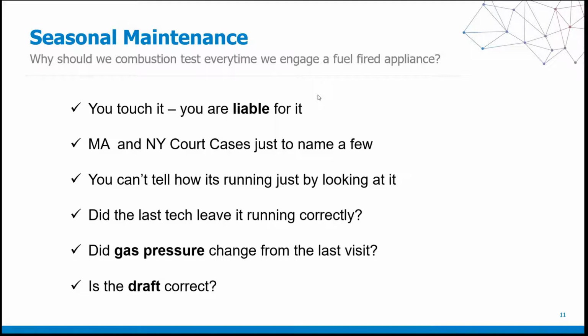First one, Massachusetts. Some of you might be aware that about 3 or 4 years ago, 37 houses caught fire and burned down in the state of Massachusetts. That was an interesting case, caused by an issue with gas pressure. I know the person who did the forensics on that case, for the plaintiff and for the defendant, and found out that normally gas pressure is delivered in inches of water column.